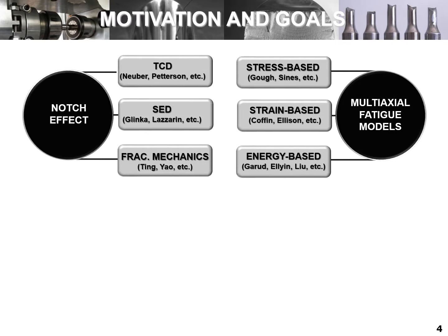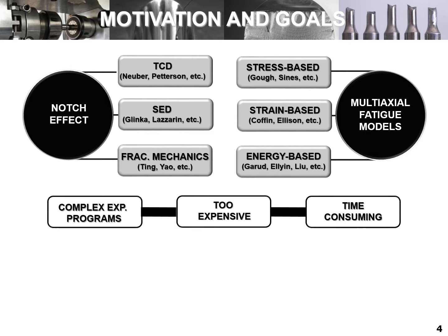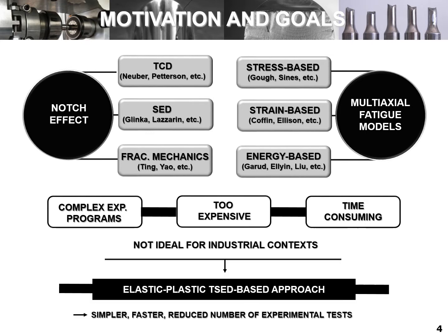Briefly, multi-axial fatigue models can be organized into stress-based, strain-based, and energy-based approaches. Regarding the notch effect, it is generally accounted for using the theory of critical distances, the strain energy density concept, or fracture mechanics. The most sophisticated models require extensive experimental programs and complex computational simulations, which can make the process too expensive and time-consuming in most cases. Our proposal aims to solve these drawbacks.